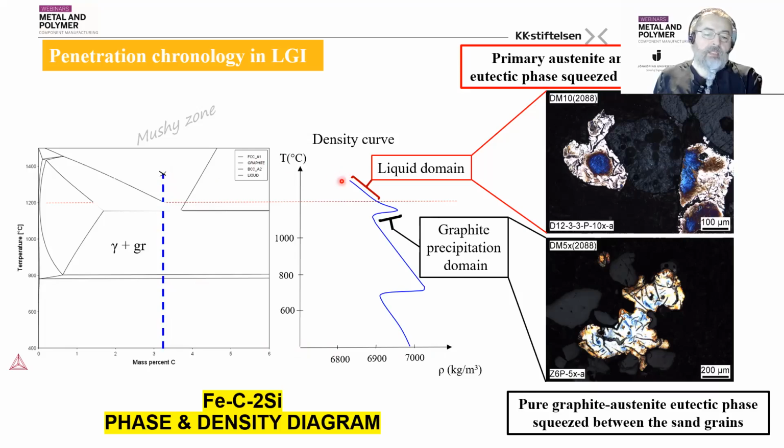The expected density in the liquid state increases due to the decrease of the liquid temperature until the solidification starts at the liquidus temperature. There the primary phase starts to form, and the density curve becomes sharper because a dense phase is precipitated from the liquid.